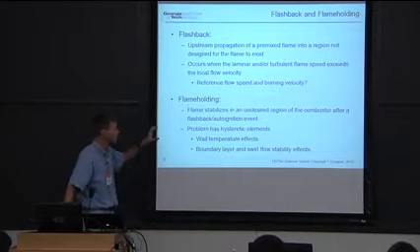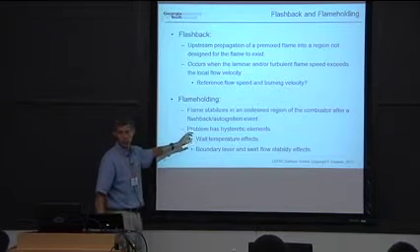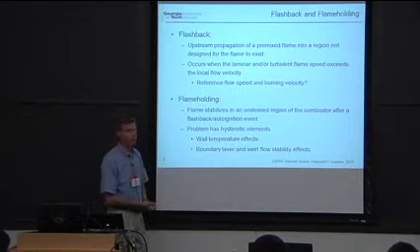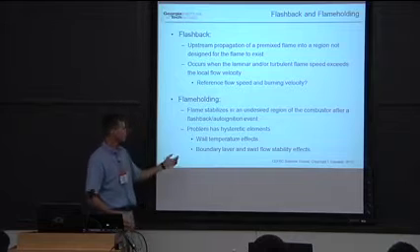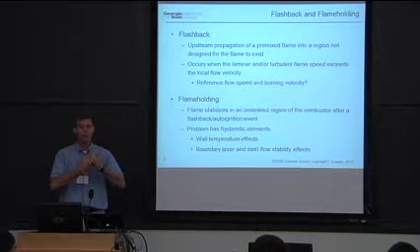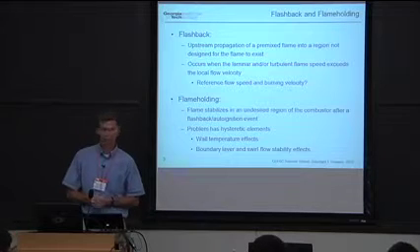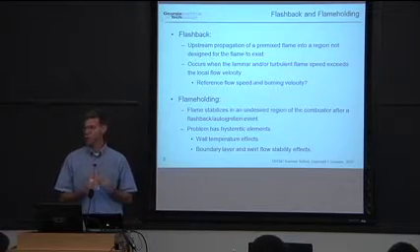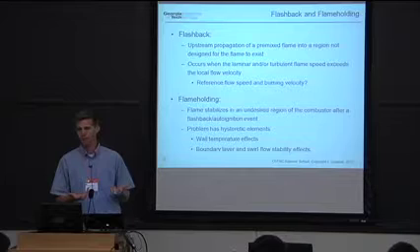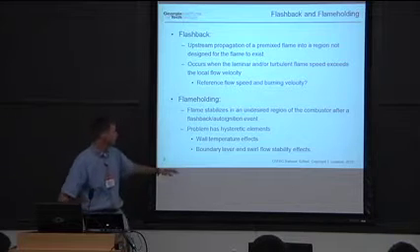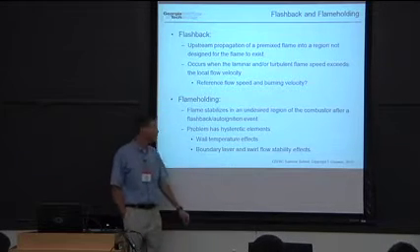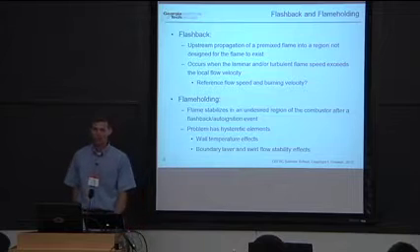It turns out that this is much harder to do because of these hysteretic elements that I'm going to talk about. For example, wall temperature effects. Once the flame comes back, it starts to heat up the combustor walls, and those walls can stabilize the flame, whereas when the walls are cold, you can't. That's one example. Another one is the effect of boundary layer and swirl flow stability.